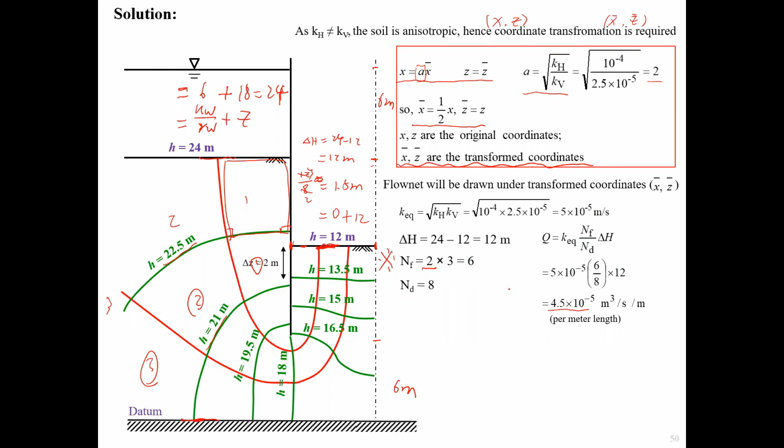And the last one, we calculate the factor of safety. Like I covered in the previous slide, we have to take this section, the toe of the dam or the section around the downstream. So only this part. Firstly, we need to take the hydraulic gradient at the base of the excavation. So i equals delta H over delta L. Delta H is 13.5 minus 12, so that's 1.5.